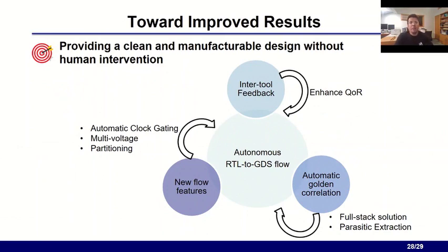As a reminder, our mission is to achieve a 24-hour no-human RTL to GDS in advanced foundry nodes, while catalyzing an open source ecosystem for researchers, tool developers, and users. Keeping this in mind, our philosophy is to make the flow autonomy central to any new development or enhancement. QoR, although coming as secondary, is expected to improve over time, and the shortcomings such as loosened timing are being addressed as we speak.